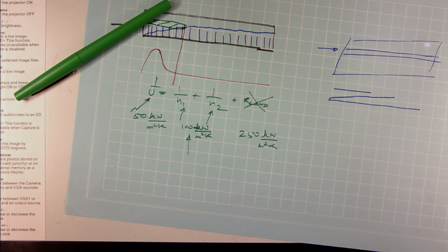Okay. So if you were to design a heat exchanger for condensation or boiling, keep in mind that the major part of the heat transfer will be only in the first 10 to 20% of your heat exchanger. All right. So you have to design it as a small length with a big width rather than a small width and a long length. Does that make sense? Okay.